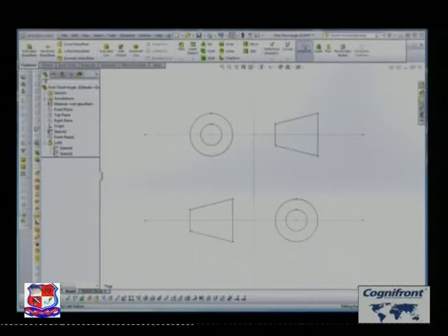The book doesn't explain it as well as it probably could, and it's helpful to have something a little bit more visual. So I'm going to take a stab at this. What you're looking at up here is a symbol. I drew this in a sketch format in SolidWorks. On the top is a third angle projection, and on the bottom is a first angle projection. Remember the third angle projection, that's a test question by the way, is what we use primarily in the United States. That's the one on the top.